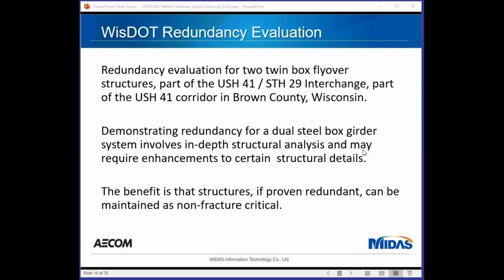The bridges had been designed as fracture critical members, so they had all the corresponding load factors, welding procedures, and specialty steels used for fracture critical members. But if we were to demonstrate that the bridges were redundant, the maintenance part could be reduced, so they could be maintained as non-fracture critical.